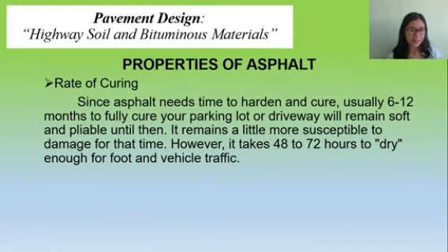So next we have here the rate of curing. Since asphalt needs time to harden and cure, usually 6 to 12 months to fully cure, your parking lot or driveway will remain soft and pliable until then. So it remains a little more susceptible to damage for that time. However, it takes 48 to 72 hours to dry enough for foot and vehicle traffic.